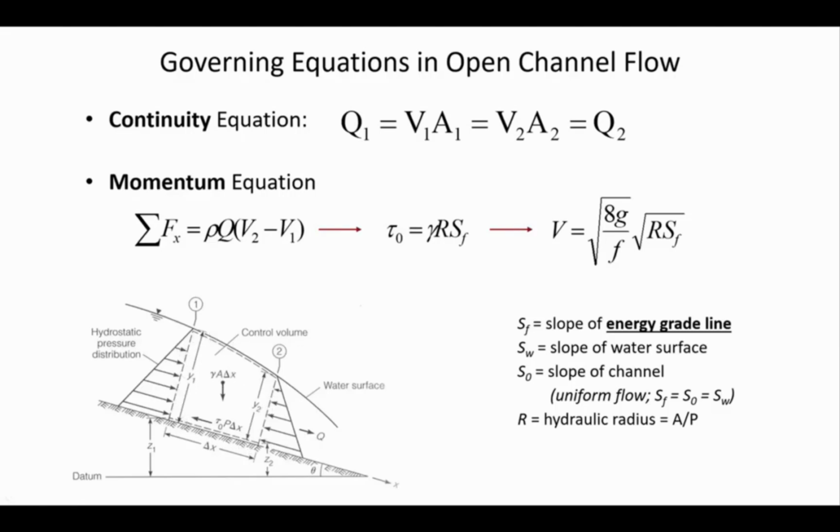And so there can't be any accumulation here if we have steady flow. So if this is non-uniform but steady, that means that the depth is constant over time, then that means that A1 V1 has to equal A2 V2. So even though maybe the velocity is faster at 2, the flow rate is the same because the depth is less.